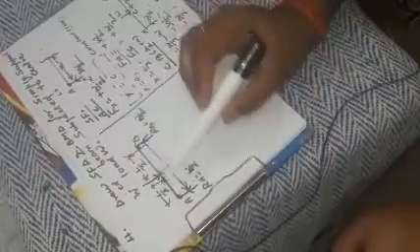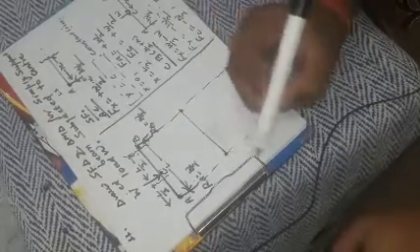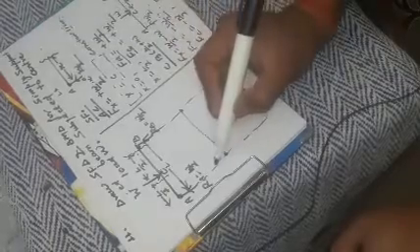Directly we can write Fc equal to minus W by 2 for X equal to 0 and Fb equal to W minus W by 2 for X equal to L by 2, right? For X equal to L by 2. So in this way, both sections are completed, both segments are completed. Now we can draw the SFD of the beam. This is your length. This is point A. At point A, the value of shear force is W by 2.